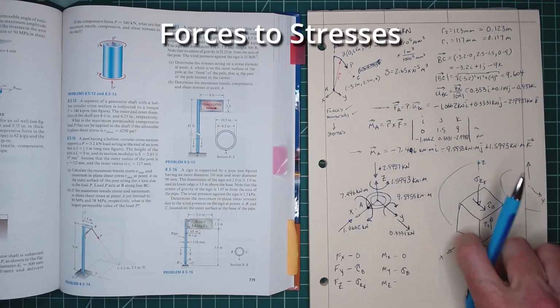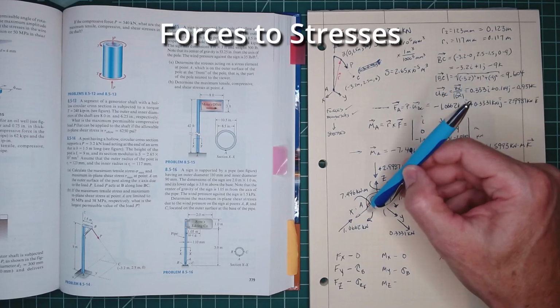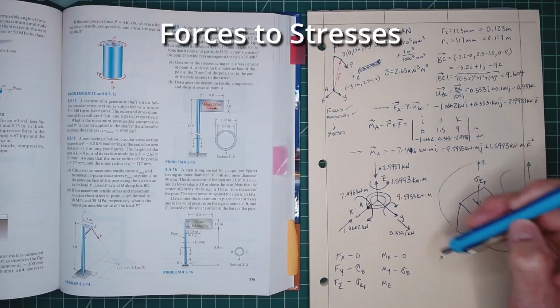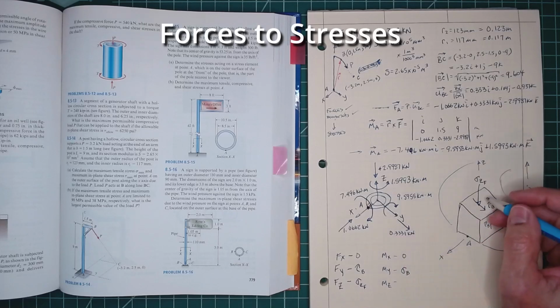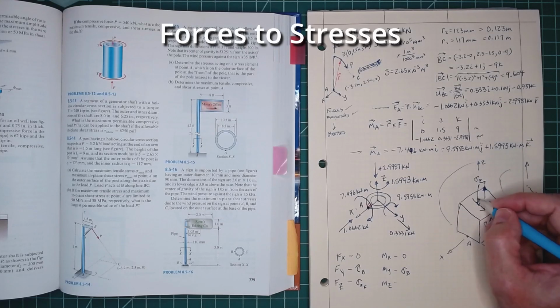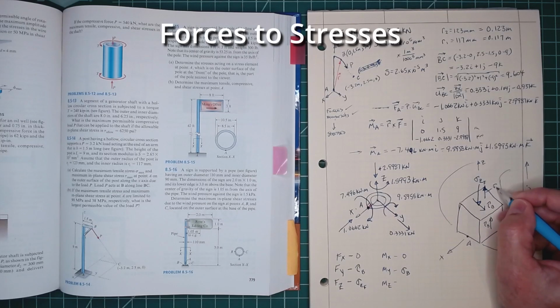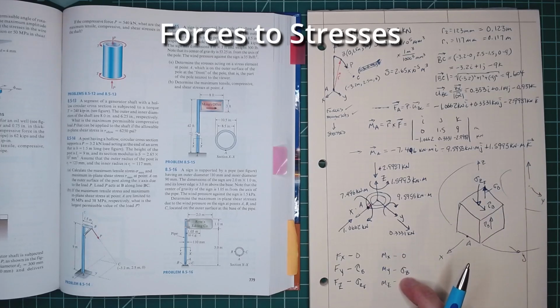Since this beam is bending this way, it's trying to stretch, putting point A in tension. So it's going to be acting on this top face again, pointing upwards, opposite of our other one. I'm just going to draw this here. This is going to be our sigma B. So that's our next stress.